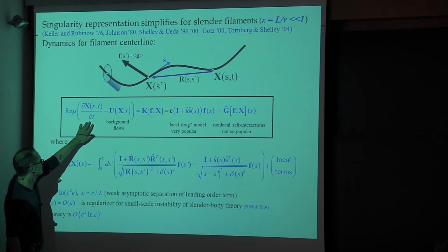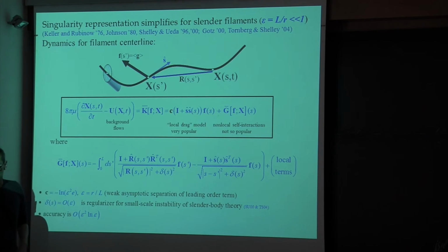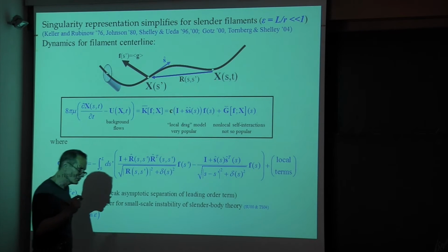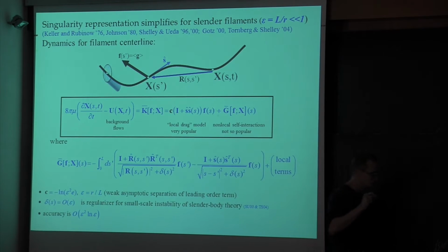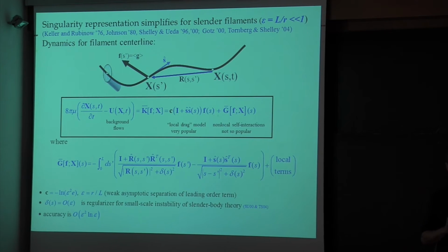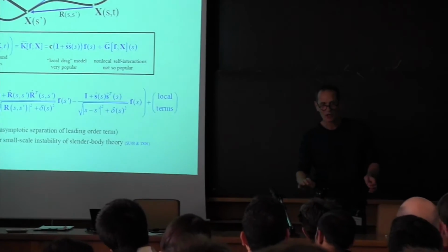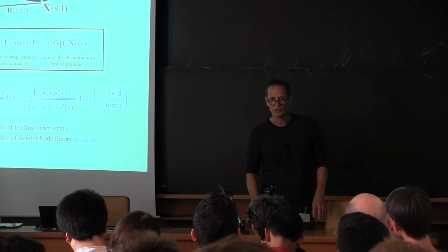Then it says the motion of the center line, the velocity of the center line, and here I'm already assuming, which I will assume henceforth, that the arc length of the center line is a material description of the center line. Let me back up a little bit. What does that mean? I didn't have to assume that, but let's say I do right now. What does that mean mechanically? If I have a curve, so I put some sort of string into a fluid, and I mark little ticks along it, evenly spaced in the arc length, and I say that those are material points.